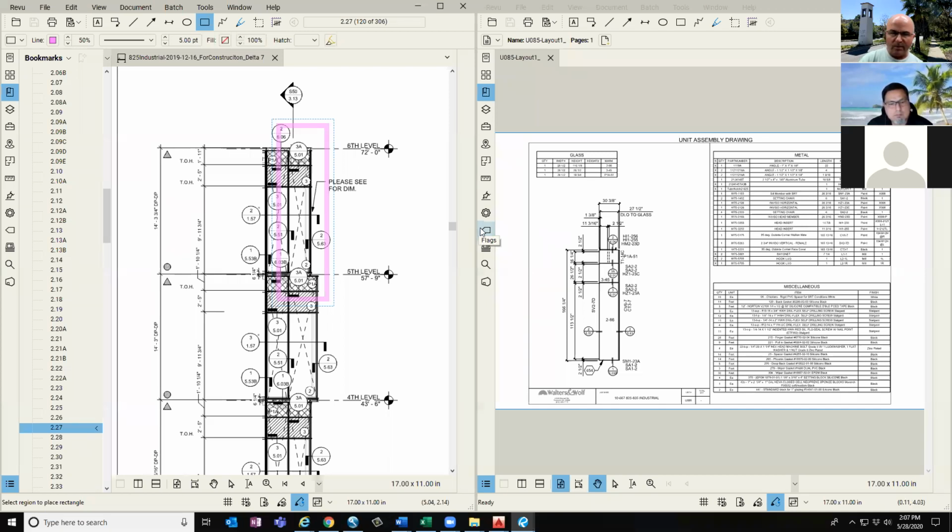So for example, we might have a sill track or a stack joint happening on one side. There might be a soffit or a parapet. Those are kind of the parameters of the horizontal connections. And then I might have a split mullion, a corner, or a jamb. There may be a transition involved. Those are basically the vertical conditions that I'm going to be looking for.